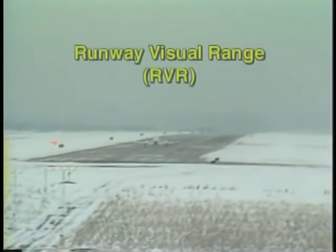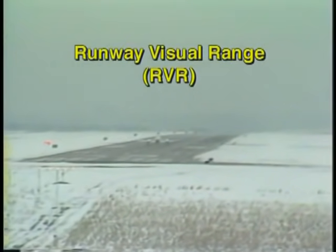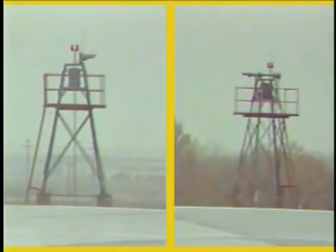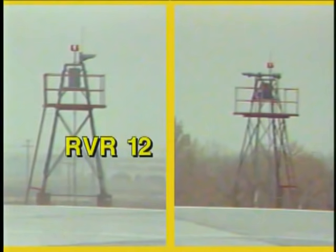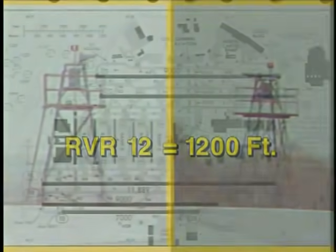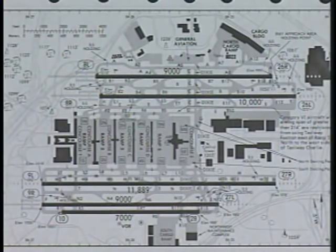The most accurate reading of visibility along a specific runway is the RVR, or Runway Visual Range. This value is based on measurements from transmissometers located near the runway and relates the horizontal visibility in hundreds of feet. An RVR value of 12 means that the visibility is 1,200 feet. Since the visibility may vary from one runway to another and at different portions on the same runway, especially at larger airports, the RVR value should be used only for the specified runway.